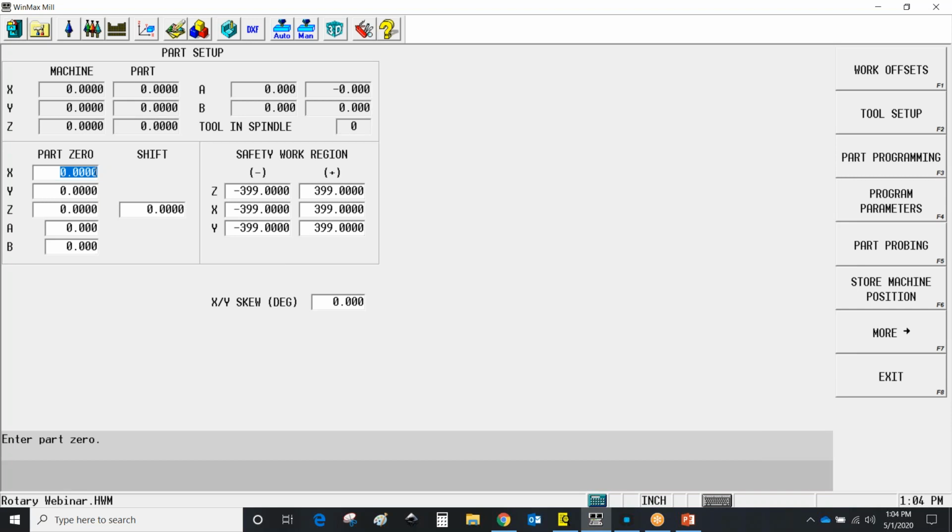If it's only a VM10 3-axis, then you will only see X, Y, and Z. There will not be a 4th or 5th. If you were to plug in an A axis, it would then show up. So a little bit of confusion comes in when we use the term Universal Rotary. People think it's only for rotary programming, and it's really not. It's just the type of programming we're going to use going forward.